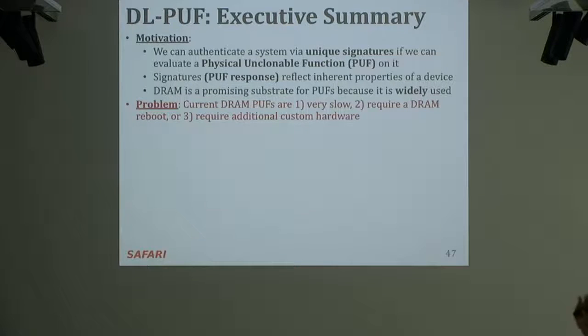Some of them are based on our work in refresh, actually, which is really interesting. The refresh-based DRAM PUFs, again, retention-based DRAM PUFs, are interesting. Some of them actually use RowHammer. Some people find that the bit errors that you induce because of RowHammer are unique to the devices, and they say that, oh, you could use this as a PUF, physical unclonable function. But then there's some other work that I've seen, that we reference in the RowHammer paper, that attacks this PUF, showing that uniqueness properties are compromised.